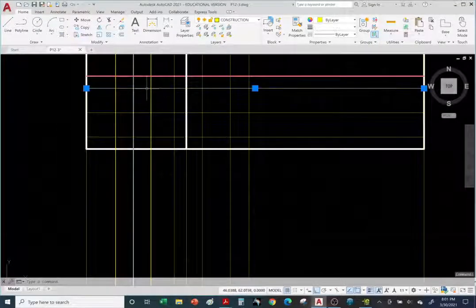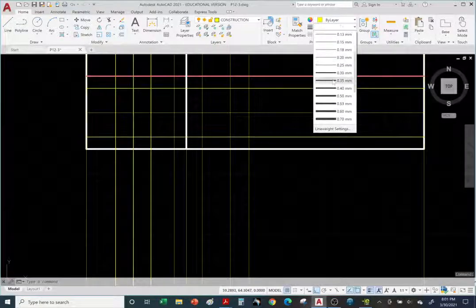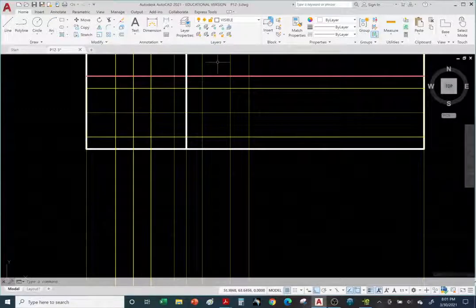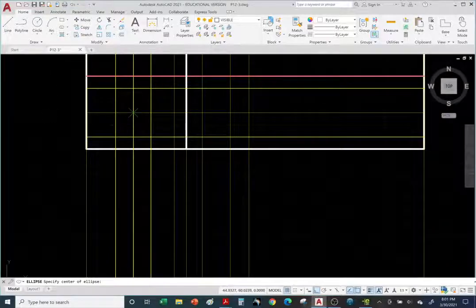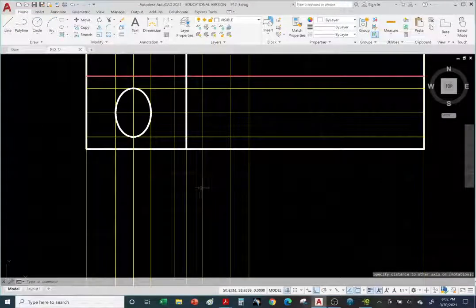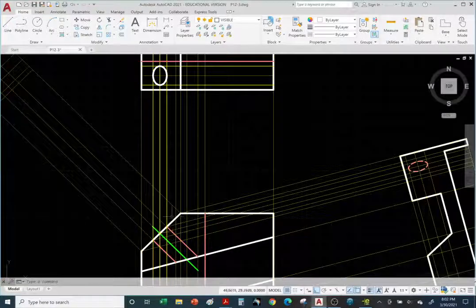We're going to use this construction line and this one for our quadrants. Let me thicken those so they stand out a bit. Hit escape to deselect. So here is our area for the ellipse. Let's go to the visible layer and use the ellipse command. Ellipse. Here is the center mark. And we can go to right quadrant or left quadrant, and then the top or lower quadrant, either one will work. And there's the ellipse, ta-da, right? And notice how it lines up with the hole in the front view.